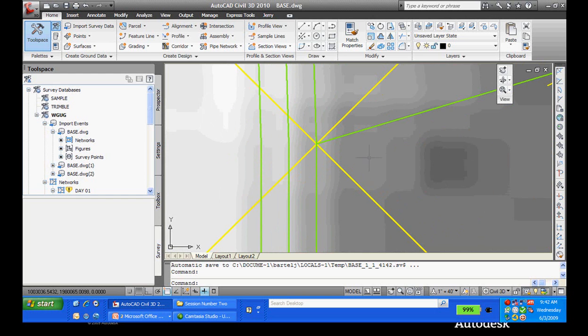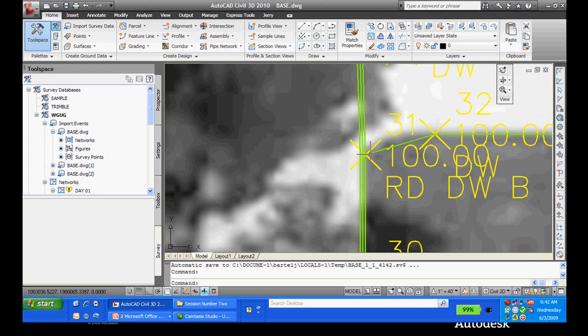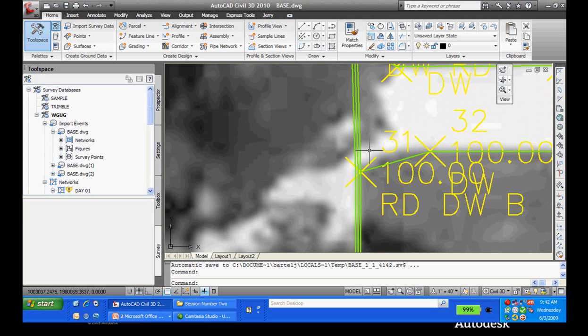Just a question: can you add that driveway point, remove the offset vertically, and adjust that offset? At that one particular point, yeah. If you're going to use the same offset, it's going to process that all the way through. So if I was going to change it, I'd have to set a new set of offsets for those. When you enter a new offset, it'll be new offsets for that point, from there to the other side, and you just pick the next one.